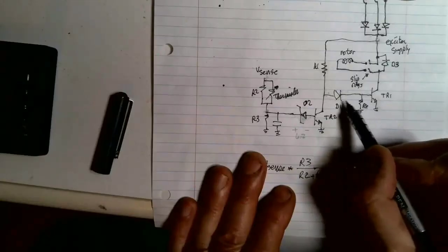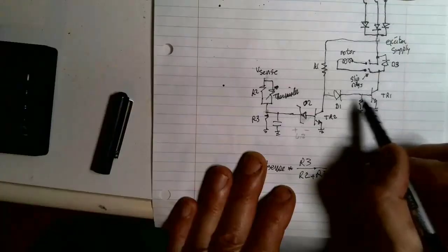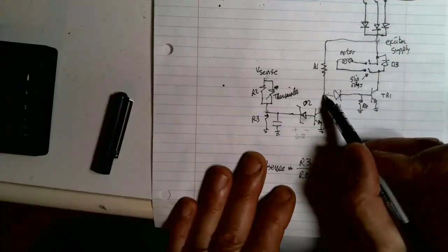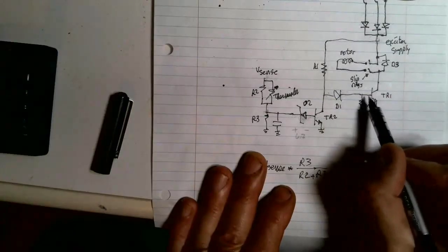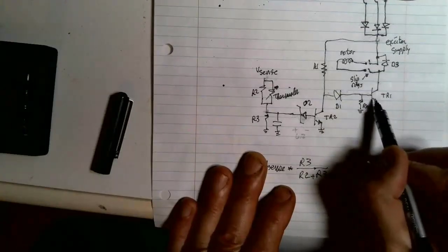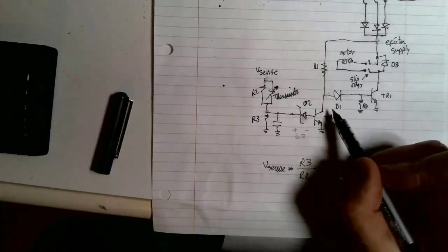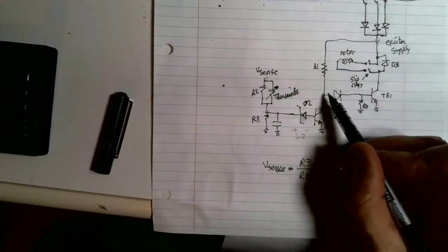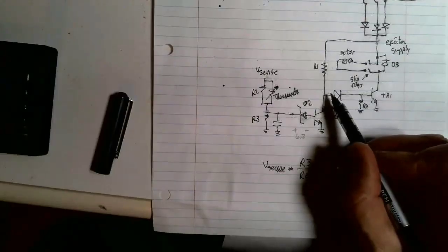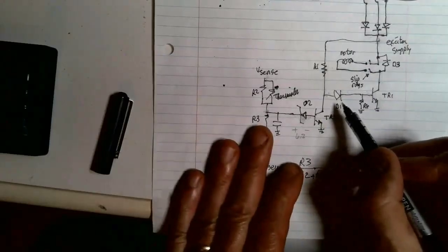So by putting this diode in here, this transistor will start to shut off when this node is at, even hot, 1.1 volts. 0.55 for this, plus 0.55 for that. So this transistor does not turn on until this node gets up to 1.1 volts, even hot, and that allows this guy's gain to be improved. I believe I read someplace they had a little issue with this transistor not being able to shut this guy off when it was hot, and that's why they put this diode in.